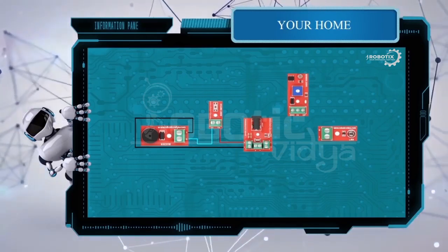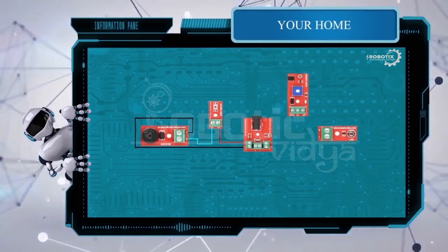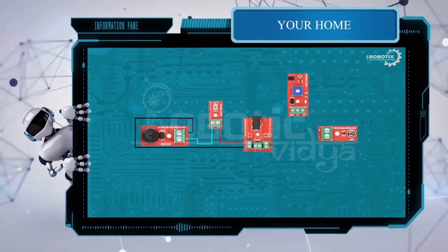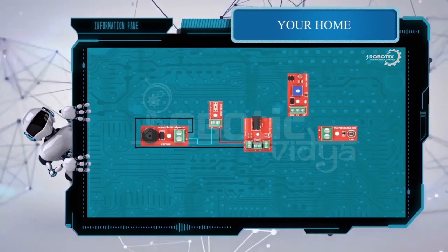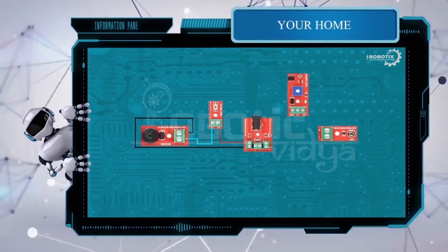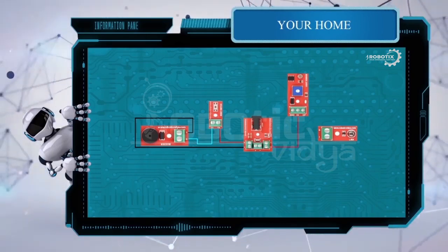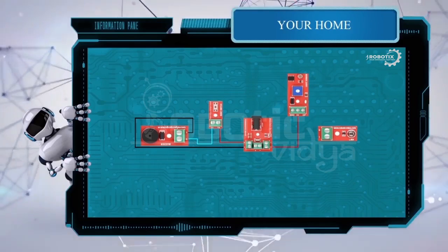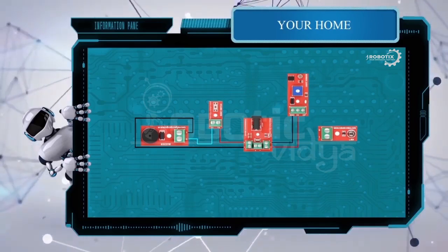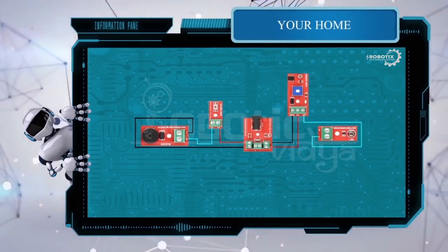The connections again are very simple. The first step in any sensor is to connect its positive and negative. So the plus of your power supply board will come to the 5 volts of your light sensor, and the negative of the power supply board will go to the ground of your light sensor.